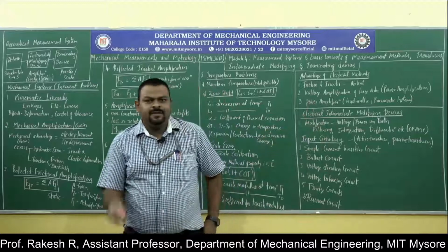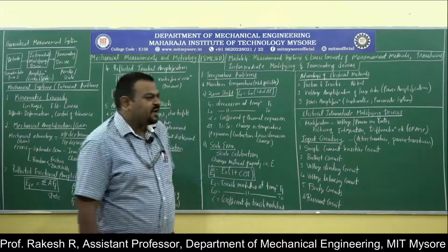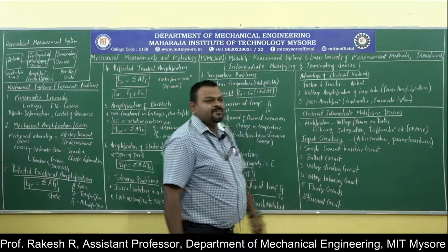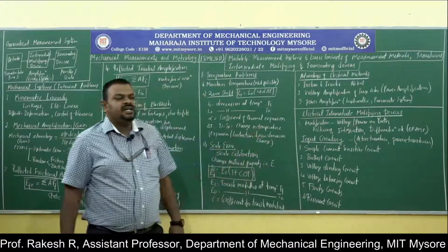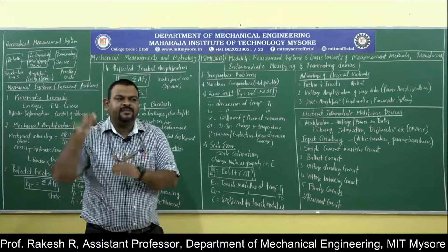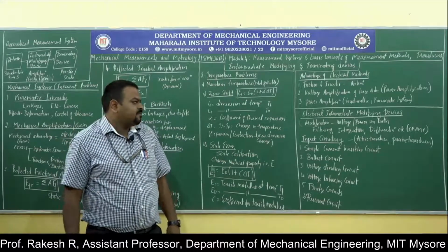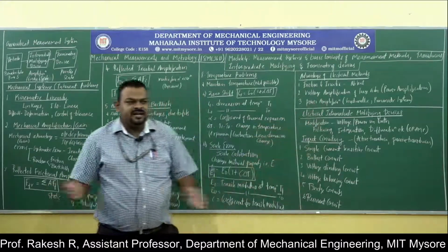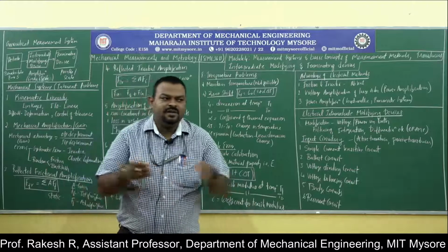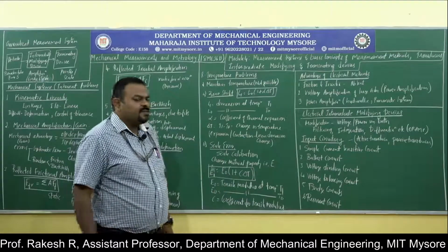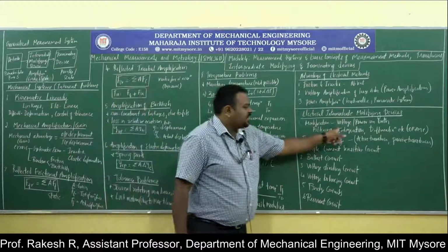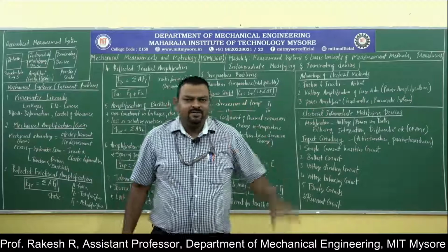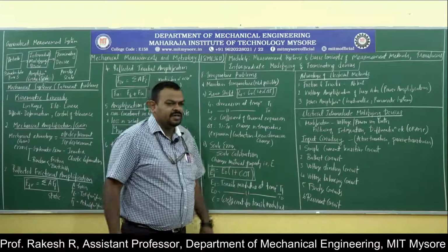For power amplification, the best options are hydraulics and pneumatics. Hydraulics for high force applications, pneumatics for high speed applications. So these are the flexibilities of electrical methods in intermediate modifying devices. Let us see what the electrical intermediate modifying devices are. In electrical, basically we are varying voltage or current. Modification is based on voltage or current or power. So V is equal to IR, you have to remember, we will be amplifying the voltage.